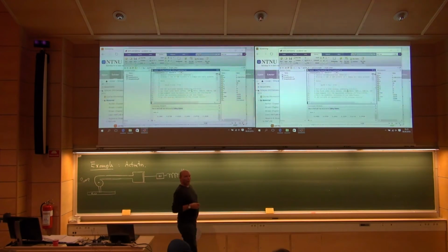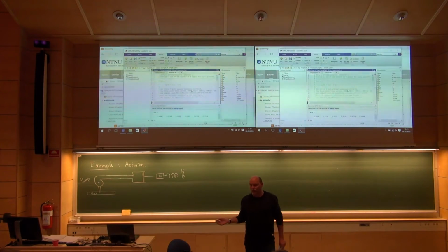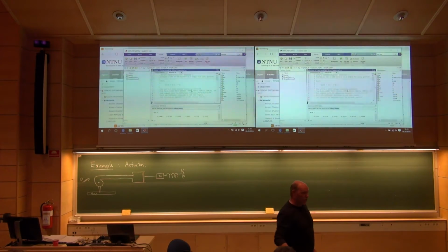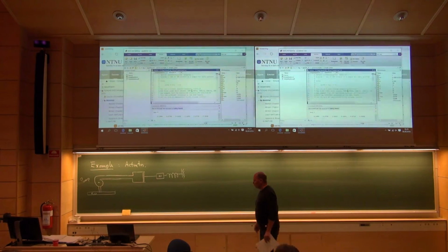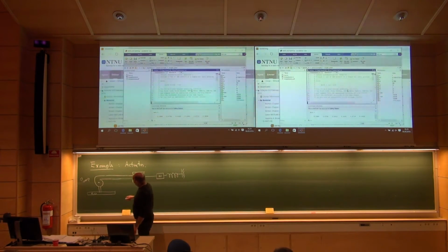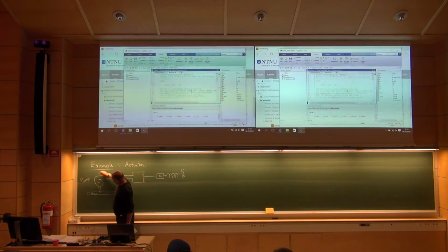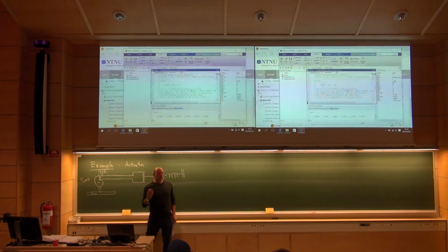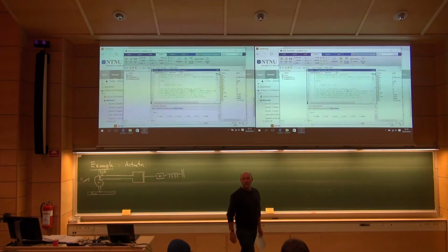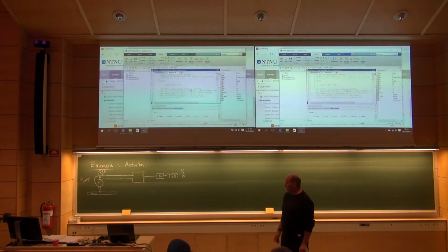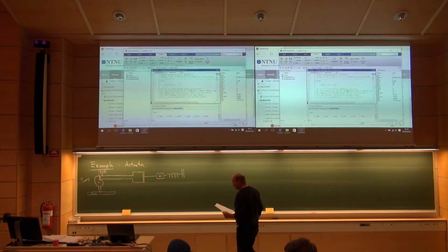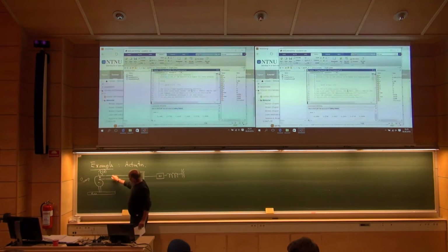This pump can, well, a pump can do two things in fluid mechanics. It can give pressure and it can give a flow, or a combination of those. But here we call this pump a pressure pump. So it specifies the pressure here, P_S as a function of time. It is given, we know it, we can control it. That's our input function into this system. So it's well known. For the pipe flow here, we have resistance